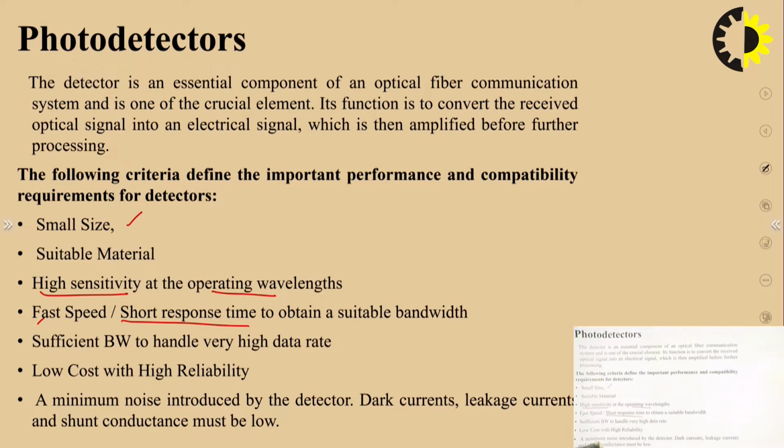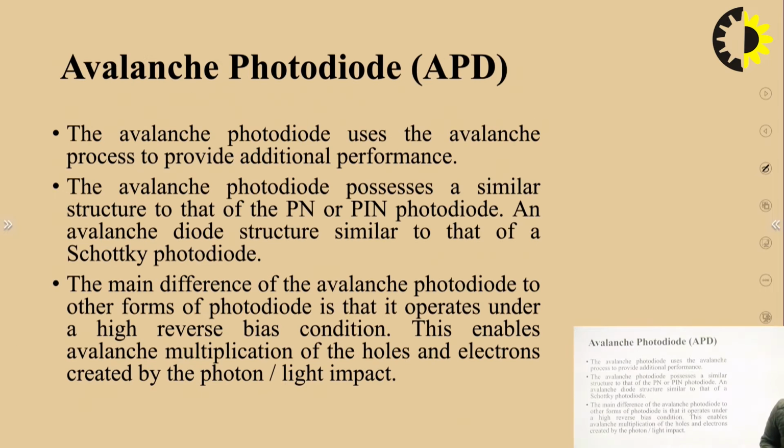Next point, it should have sufficient bandwidth, which is essential to handle a high data rate. The photodetector should be low cost with high reliability, and minimum noise should be introduced by the photodetector so that the SNR will become higher.